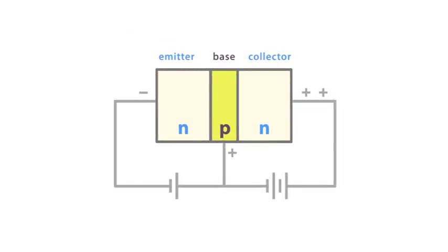When the transistor is on, the emitter-base junction is forward biased and the base-collector junction is reverse biased. Free electrons in the N-type emitter move away from the negatively charged emitter plate into the P-type base, where some recombine with holes, producing a small base current. Most electrons cross the base into the more positive collector, resulting in a much larger current between the emitter and collector. Positive holes travel from the base to the emitter.